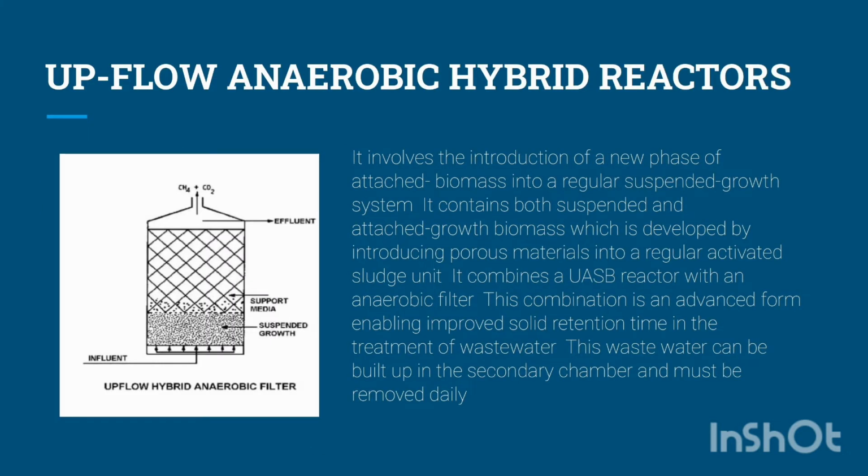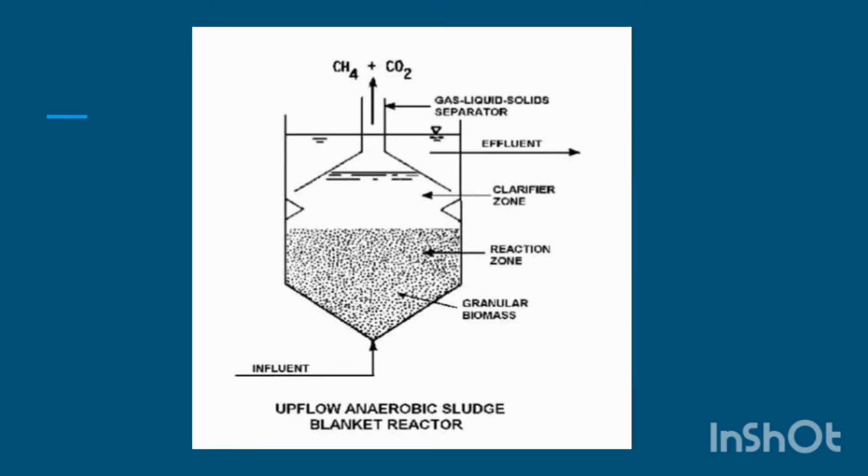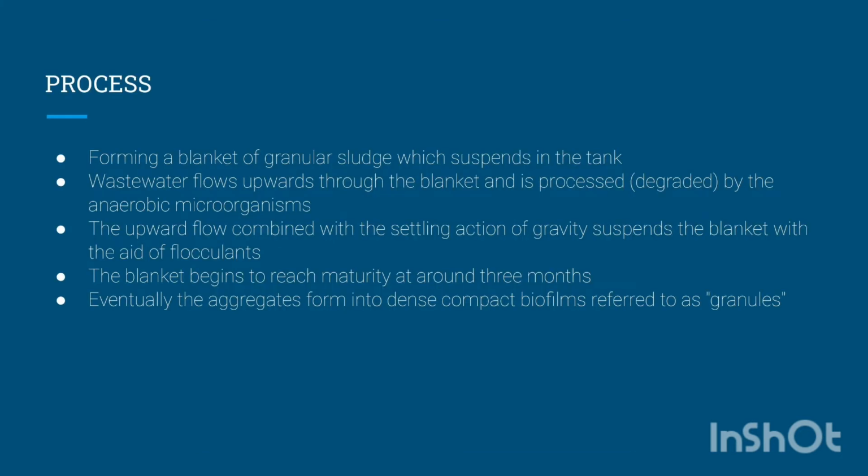The UASB reactors are typically suited for high strength wastewater, but are still used for domestic sewage in warm climates. They differ from other anaerobic reactors because of the existence of granular sludge with high methanogenic activity, high mechanical strength and good settling properties.